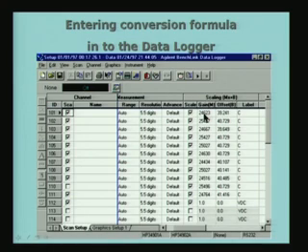So, in other words, the conversion formula from voltage to degree Celsius is different for this thermocouple as compared to this one, because the values are slightly different. You can see that it is so for almost all of them. So, all the 11 cases or 10 cases whatever we have got here, we have got the values of gain set here. In other words, this is the software which is going to do the background calculation.